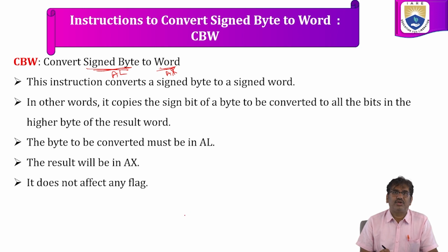In other words, it copies the sign bit of the byte to be converted into all the bits in the higher byte of the result word. The byte to be converted must be in the AL register. The result after conversion we can see in the AX register. It does not affect any flags.